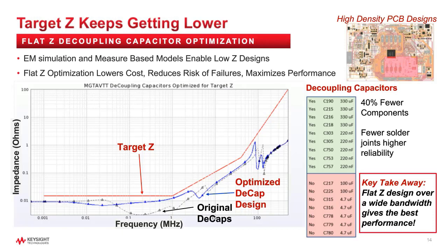The PI designer only has control over the range of frequencies covered by the voltage regulator module and the printed circuit board decoupling capacitors. The challenge in selecting the decoupling capacitors is that at milliohms of target impedance, the PCB routing parasitics and component package parasitics can be significant. Simply leveraging the decoupling capacitor recommendations from a datasheet may no longer be accurate.